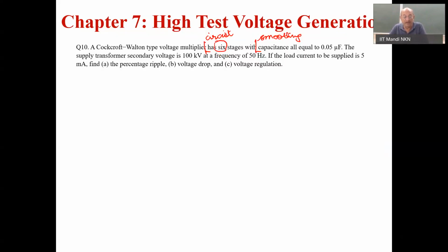So this is a very high voltage generator having 6 stages. That means the number n here is equal to 6. So a slightly different calculation will be there. Delta U will be given by I upon 2FC, and the number of stages in series works out to be n into n plus 1 upon 2. So you take care about that and attempt.